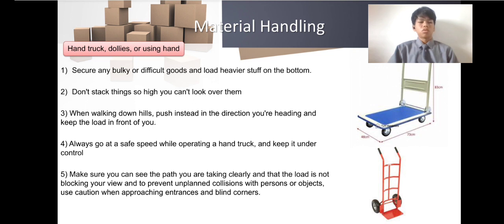Keep it under control. When you are going to operate the hand truck, you must go at a safe speed and keep it under control, because if you go too fast and do not have it under control, you will get injured and have an accident. So make sure you see the path you're taking is clear and the road is not blocking your view, and